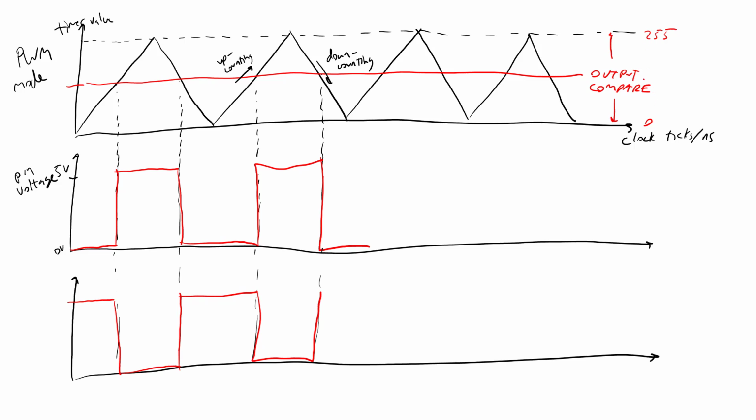can be between 0 and 255, and say I increase that. Okay, I'm going to increase it up here and make it higher. Well, if I, again, trace down where these are going to cross, in this case, making that higher is actually going to decrease the duty cycle. So it's kind of an inverse relationship, making this number bigger. Again, where this is a value between 0 and 255, and our duty cycle is going between 0 and 100%.